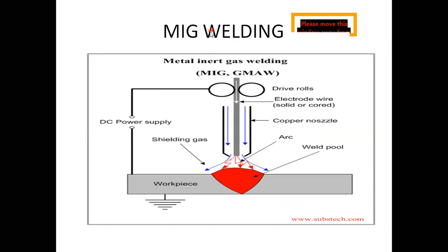When you put metal in this arc welding, the filler metal melts and fills the gap. But what happens? Some inert gas surrounds this area to cover it up, or you may say this is for shielding, so that the nitrogen and oxygen do not come in contact with this filler material.